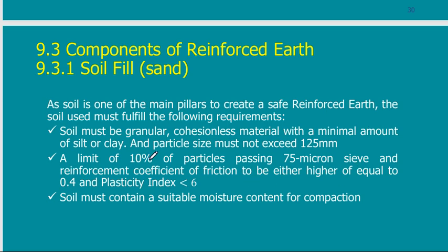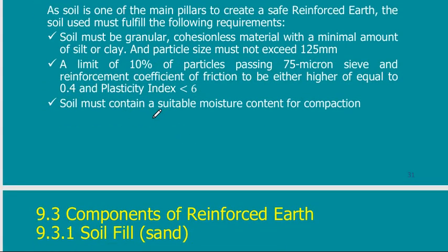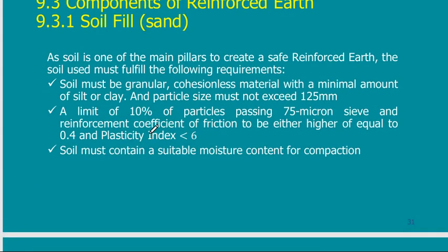a rough estimate for it. So what are the components of this? We said that the sand. Of course, sand should have quality. I'm not going to bring any sand and use it. One of the most important things is the fine particles. If, instead of using sand, you use silt or clay, no, you cannot do this.